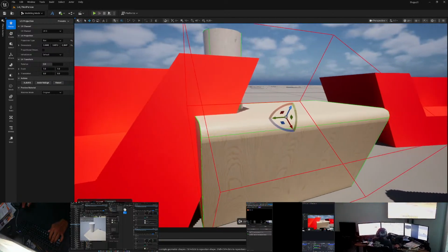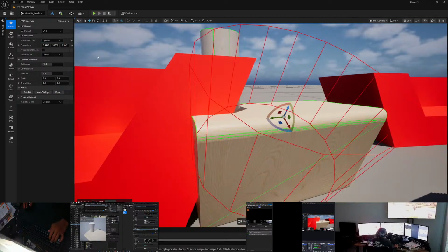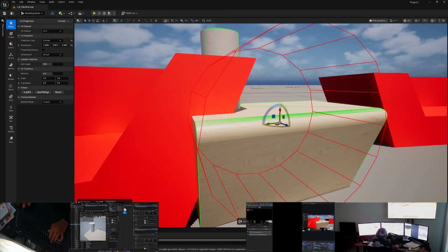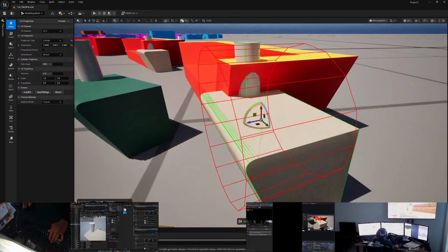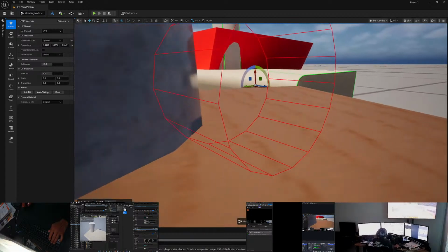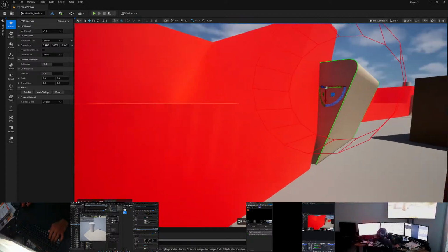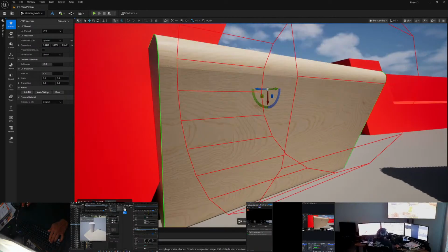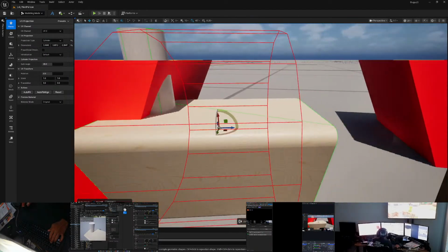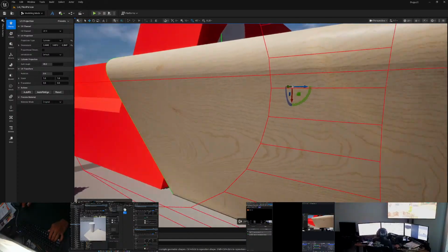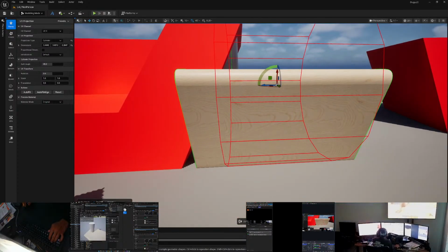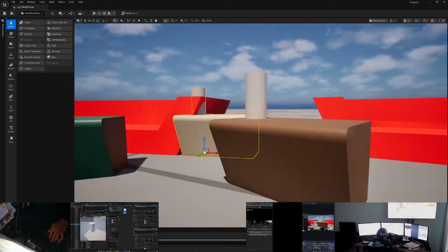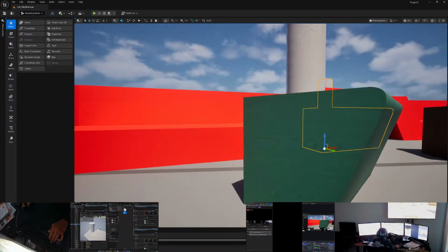Or alternatively, I can do something like a cylinder, auto align, enable that 45-degree, rotate it this way, and that might give me a more accurate projection around the whole thing. Okay, accept, and now all of my meshes have gotten updated.